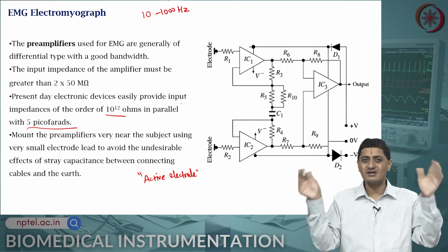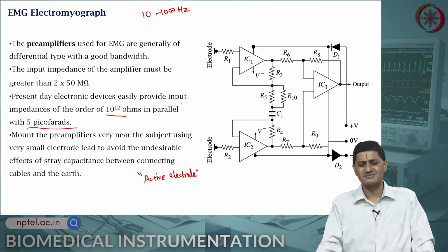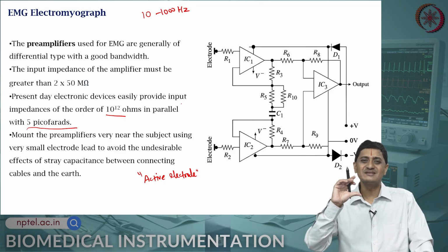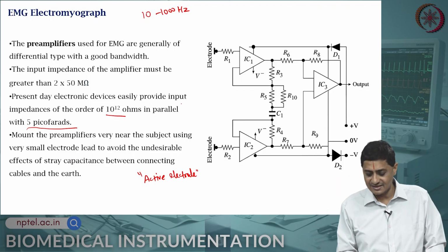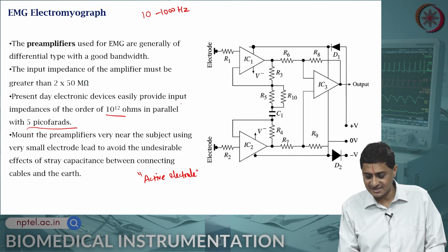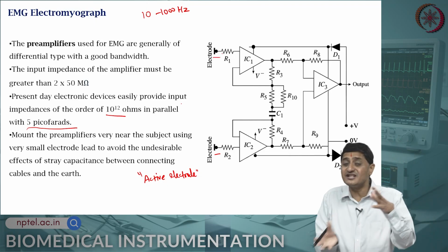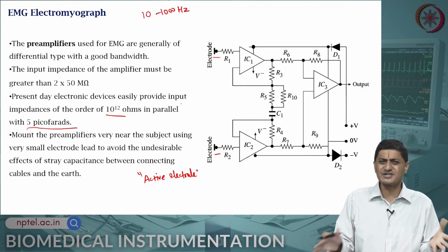So, the extra sounds, extra noise that he is hearing from all the other people can be considered to be common mode noise, and that will be rejected, essentially will be subtracted. That component of the signal that is available in both the electrodes will get subtracted, and only the difference between the two will be amplified. That is the fundamental function of a differential amplifier.